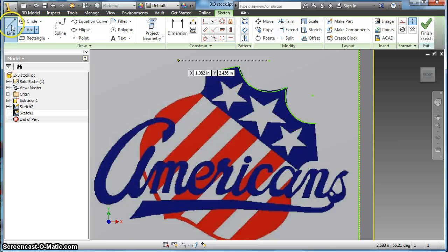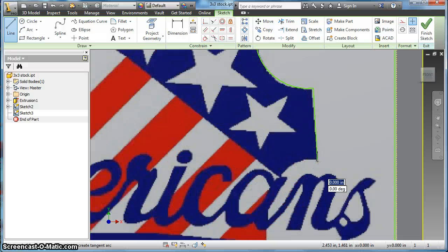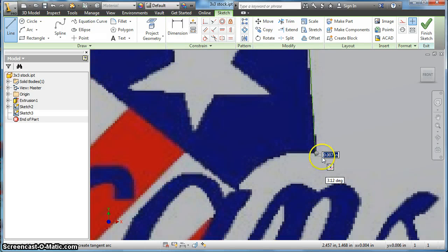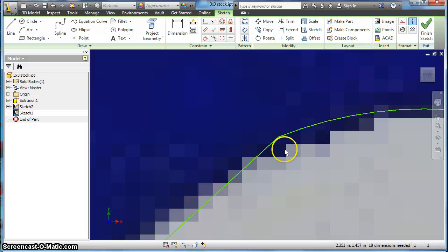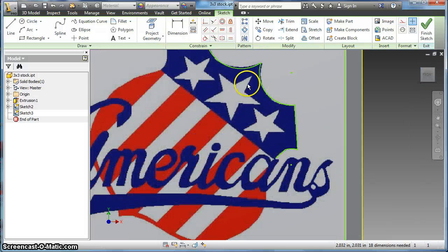and depending on how the better you are with the shape, the more accurate it will look. So here I have a complex curve, so I probably want to make this arc in two sections. And you can put the arc in there and drag the edges of it, and then maybe add a line that comes down. Right? You want to make sure that everything connects. If you have any gaps, it's not going to extrude.